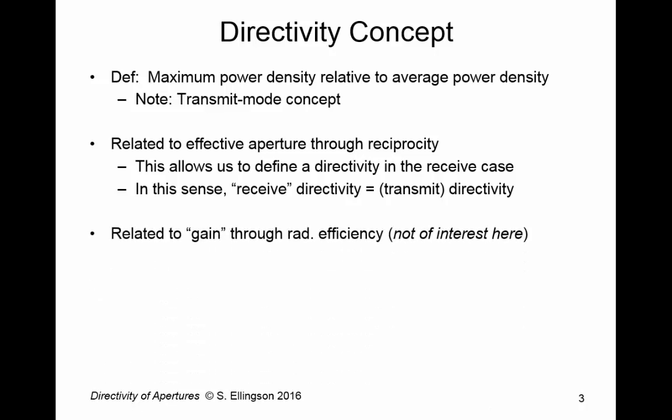Of course, directivity is also related to gain through radiation efficiency, and we're not going to really address that here. That's a relatively simple concept, and I'd like to separate it from the current discussion just to keep things simple. Also, no doubt you recall that directivity can also be used as a pattern metric. In other words, we don't have to think of directivity as being the maximum directivity over the pattern angles. Now, we're not really interested in the pattern application of directivity. More often, we use normalized field patterns or normalized power patterns for that purpose.